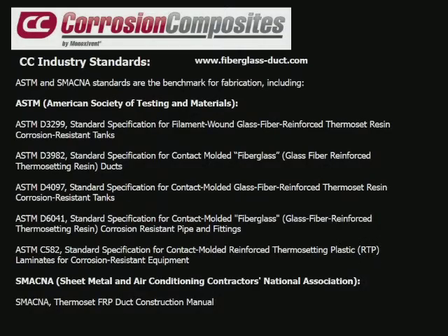What we're looking at here are the industry standards. The corrosion industry really got its start in the 50s. Some of the fiberglass tanks that were built back then are still in service from the 1950s. The ASTM standards all arose from an old standard called PS 1569, which some of you may have heard of. The ASTM standards cover pipe, tanks, duct, and your ASTM C582 is the critical one. That's the last one on the list there from the bottom.